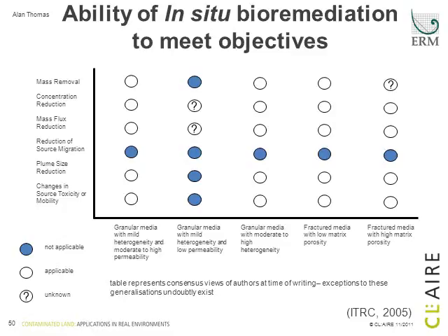Very often, once you've completed your site characterization efforts and undertaken some initial work, the next step in the remedial design process is undertaking some kind of feasibility screen. There are a large number of various matrices and checklists that you could use to evaluate whether your technology has the ability to meet your likely cleanup objective given your hydrogeological, geological and chemical setting. This is just an example of one output from that process.